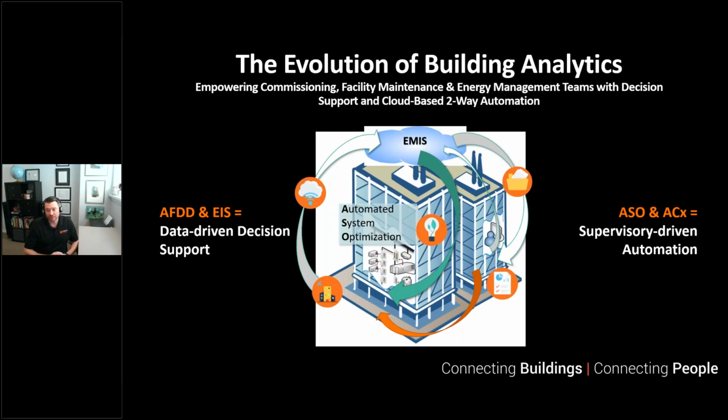Basically, that is the resolution for some issues. Of course, if it's a mechanical fault, a leaking valve, or a damper stuck, then there's no automation that will fix that until we get robots that are going to crawl up into ductwork. But in the meantime, anything related to optimization, to do with schedules, set points, staging, etc., as we will discuss along the rest of this presentation, can now be automated from the supervisory platform down into the building automation system, shortcutting a lot of that back and forth and really enabling a much faster resolution and return on capital for these projects.